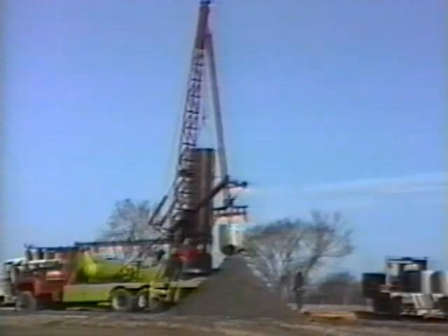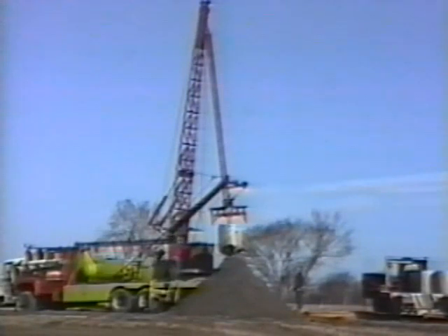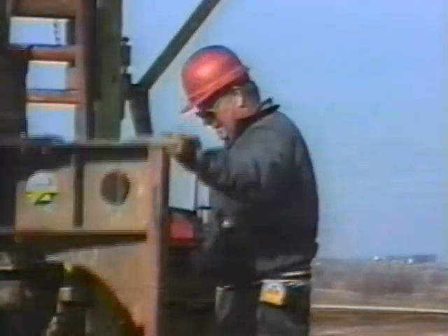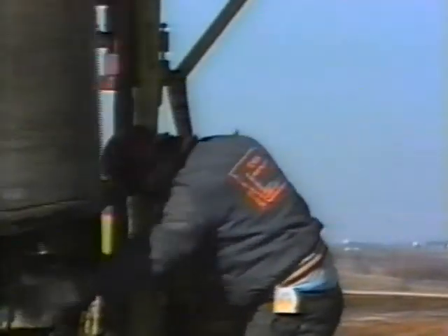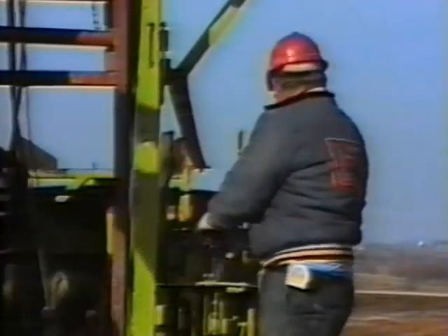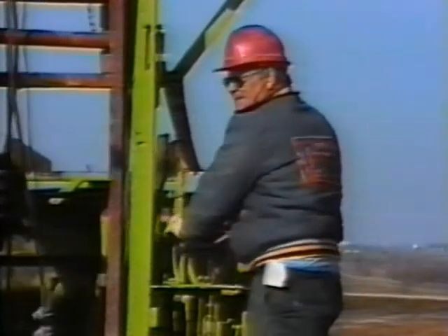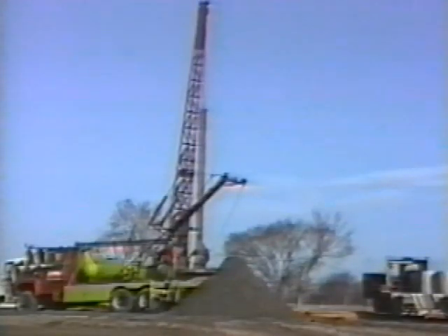During the drilling process, the hole may require the installation of temporary or working casing to stabilize the hole until permanent casing is installed. Drilling continues through the working casing, using a smaller bucket until such time as an adequate aquifer is located. The 4 telescoping sections of the Kelly bar enable the bucket auger to drill up to 100 feet in depth without the use of additional Kelly bar sections.